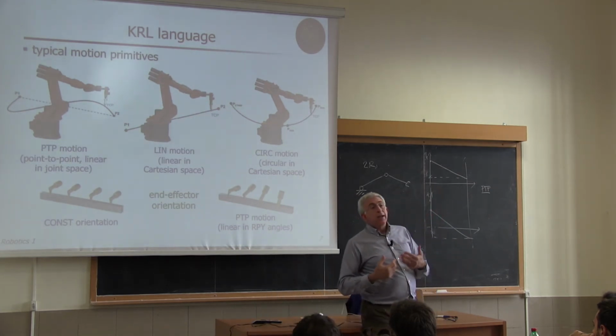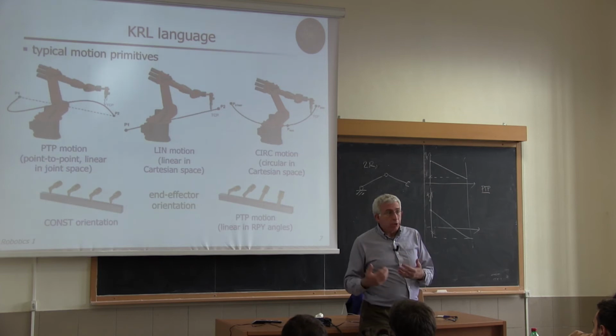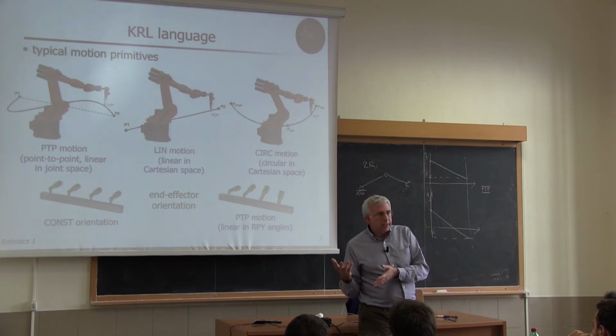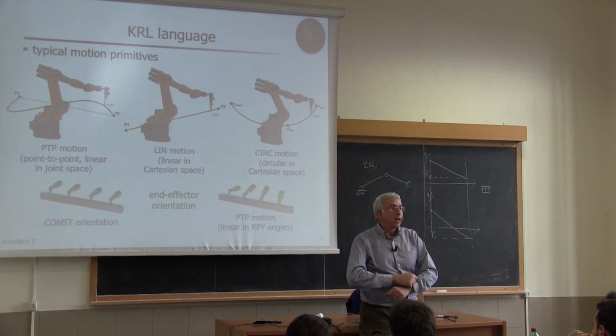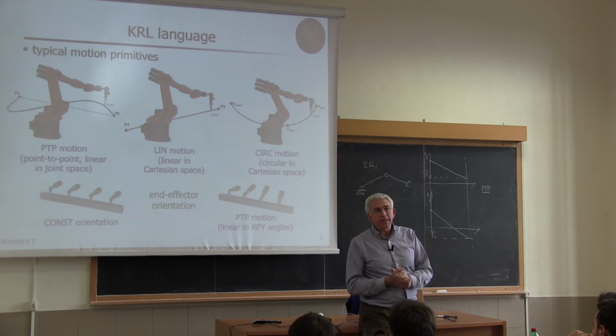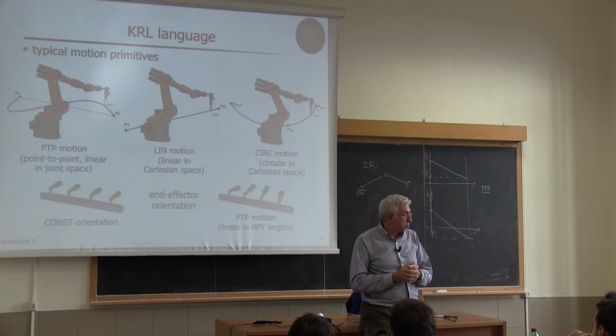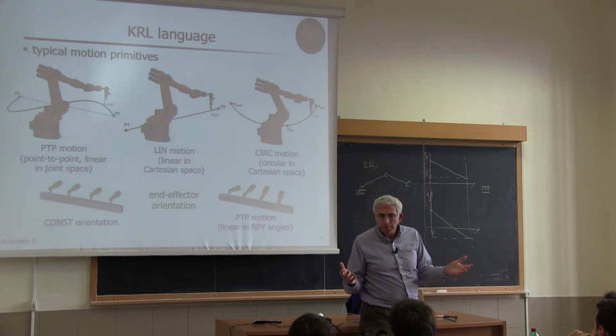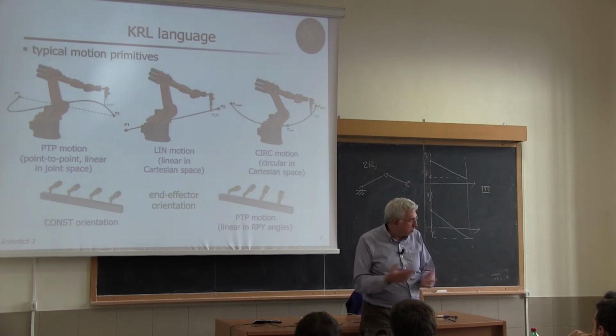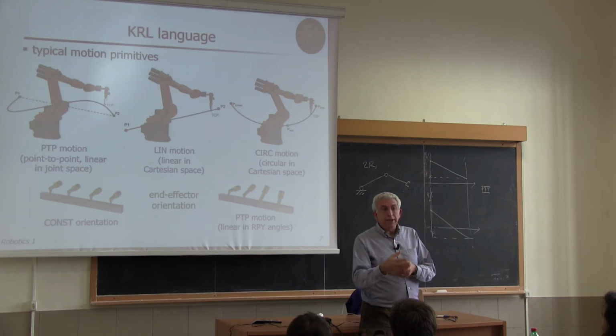This is why offline programming and simulation is very important, because you can discover some problems in advance. Otherwise, the robot will start executing the task and all of a sudden have increasing speeds at the joints until it saturates and some protection goes on and the robot stops. And this is something that you don't want to have when the robot is online executing some task.